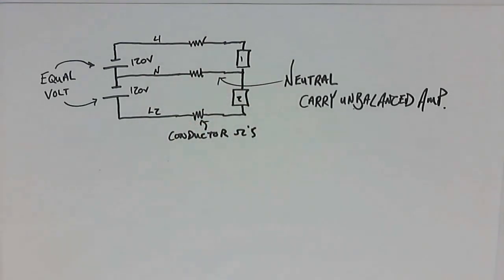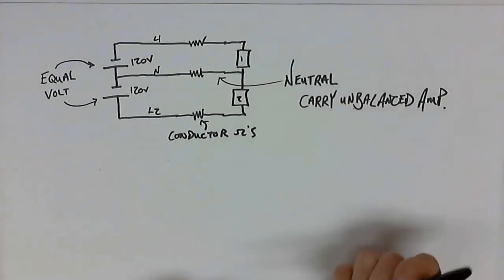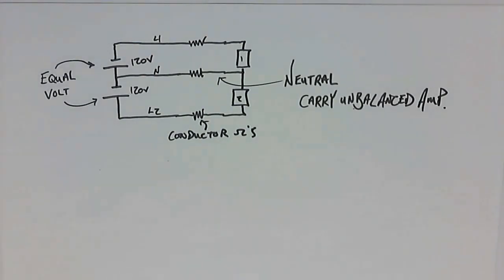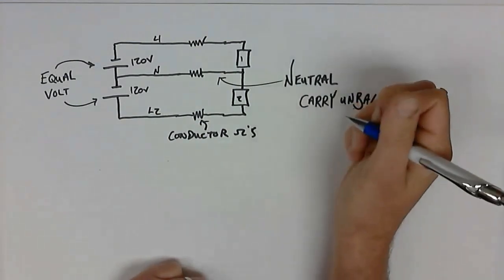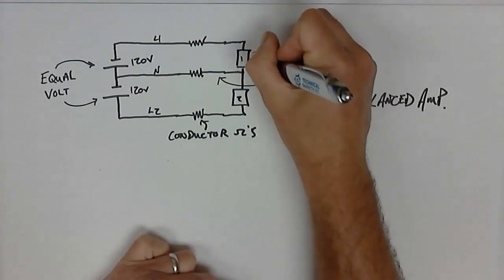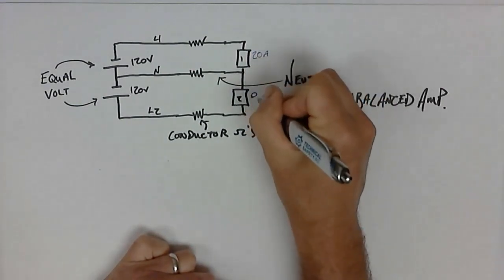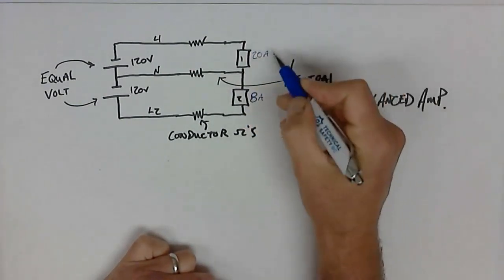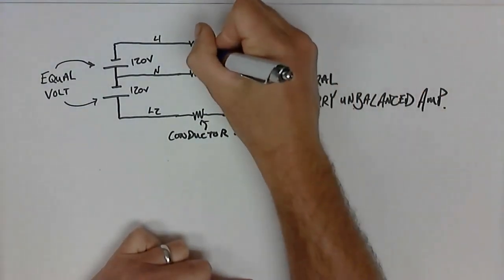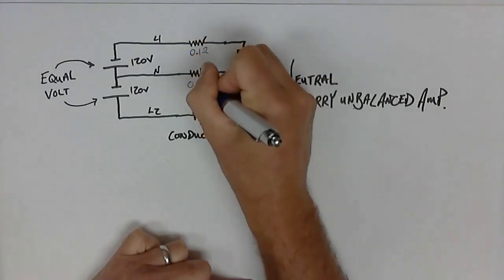All right, so what are the steps involved to calculate the voltage across my 2 loads? Well, first thing we have to do is assign a value of current, and I'm going to choose values of, let's say, 20 amps and 8 amps. And the resistance I'm going to choose is very small, 0.1 ohms for each one of my conductors.